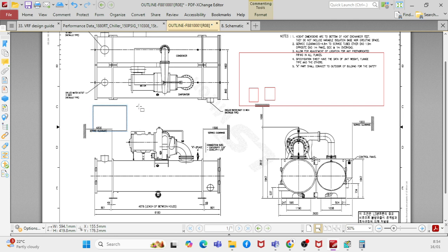For a water air cooled chiller, you have to go with at least a 1000 kilowatt chiller, with around 8 or 9 meters in length and approximately 2.4 meters in width. Then you would have five units next to each other. That means your entire space is basically being taken up.